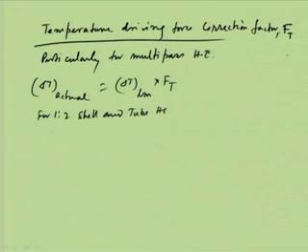shell and tube heat exchanger, we have a relationship. 1:2 means, as already discussed, 1 is the shell pass and 2 is the tube pass. And what is this pass? Pass means how many times the tube fluid is passing through the heat exchanger. Twice, the same fluid element is passing through the heat exchanger twice, which is why it is called 2 pass.